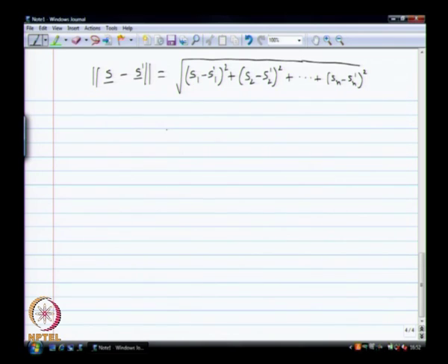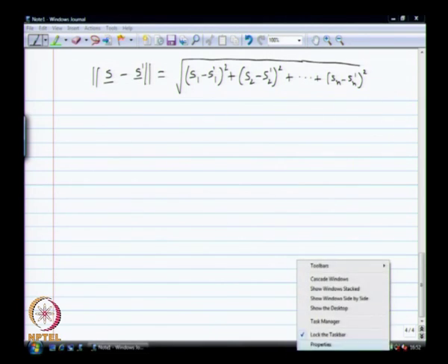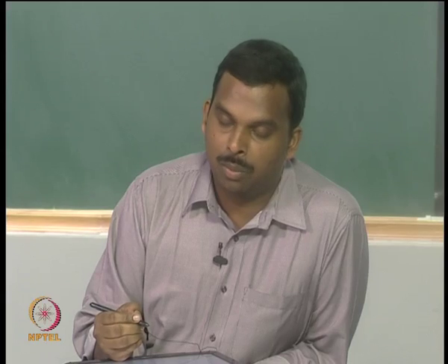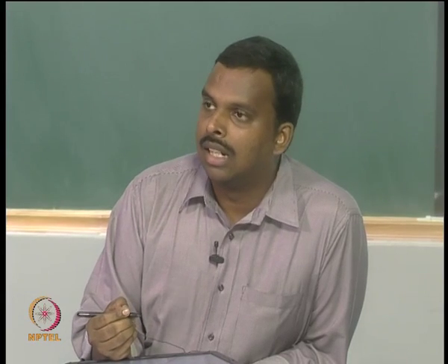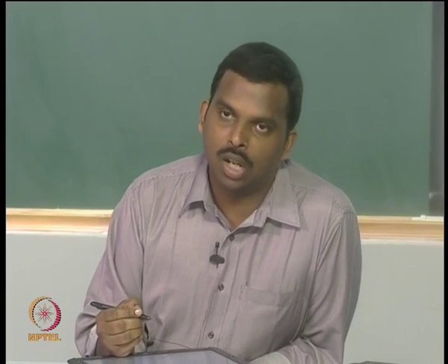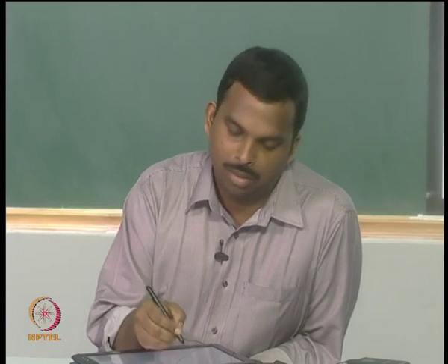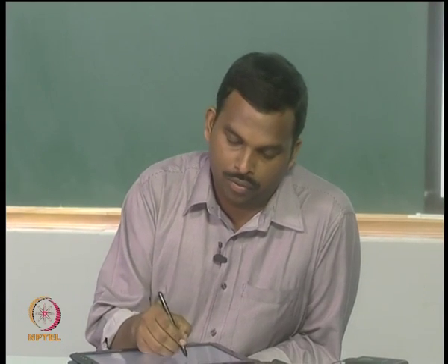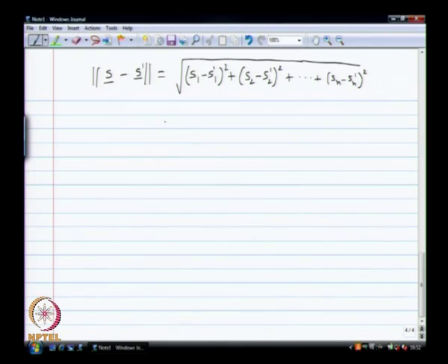So it turns out if you now know the Hamming distance between C and C prime, you can use that to write this precisely. After all you are doing BPSK, so you know S1 and S1 prime for instance are plus 1 and minus 1, and if the two code words did not differ in that first position, the difference will be 0. If it differs, it will be 2. So it will basically be 2 times the Hamming distance between C and C prime.